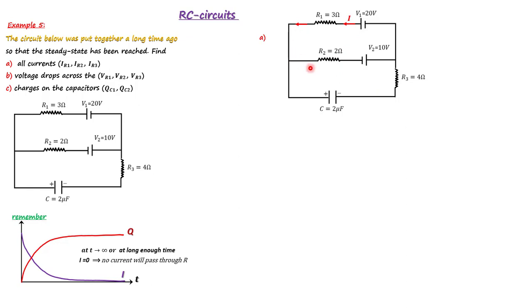So the current produced by this battery flows around through this circuit. So this region is forbidden. Now we have this simple circuit. You see we have two batteries, but they are in the same direction. They are pumping the current in the same direction. If you like, you can use your Kirchhoff's law. So direction of the current and direction of the loop will be the same.